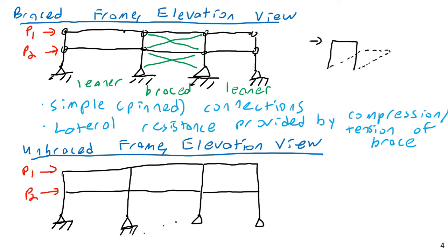Let's finish drawing the soil or the foundation here, showing that we are transferring the load to the ground. Well, the only other option is that we have to stiffen up the connections. And so what we're going to do is make the connections moment connections. Now I'll draw them as all the connections, but it doesn't have to be. You can use just some of the connections as moment connections, and in most buildings that's what you actually do.